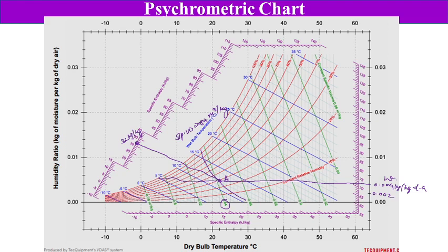So this straight line is the specific volume line. This is how we can get the information using the psychrometric chart. From here you find dew point temperature, enthalpy, specific humidity, humidity ratio, and dry bulb temperature is here. So these things can be obtained from the psychrometric chart also. Here we stop, and in the next class we will be looking at psychrometric processes. Thank you.